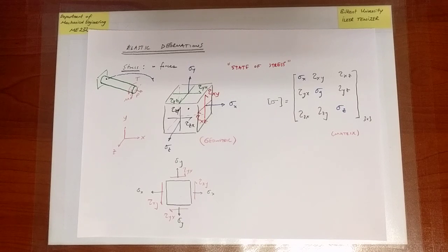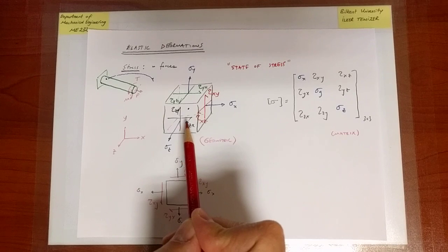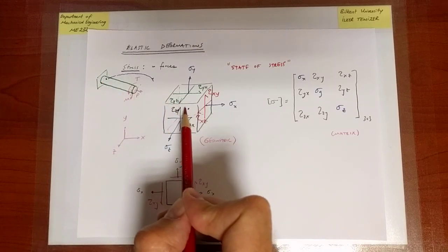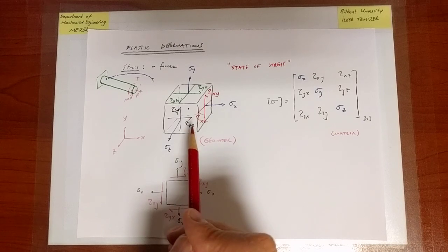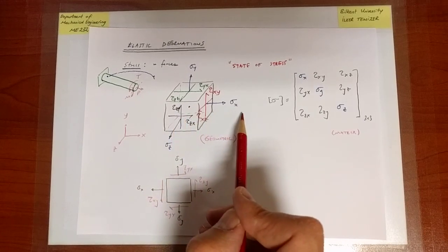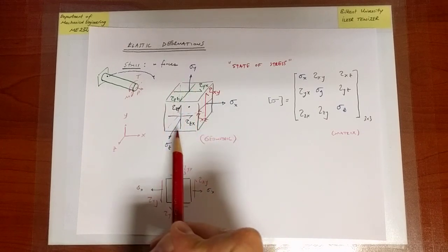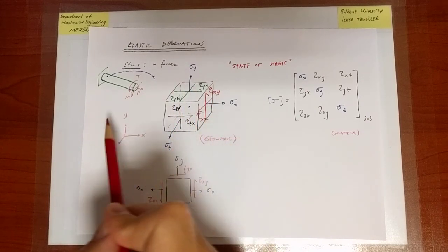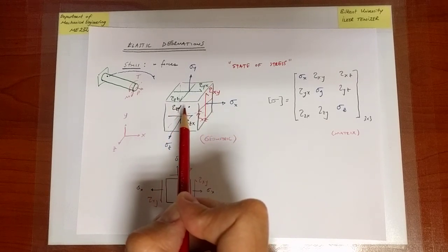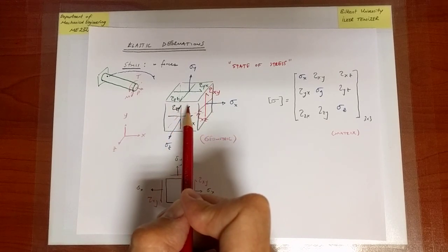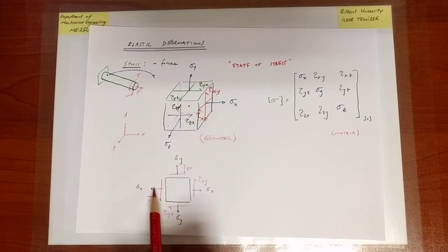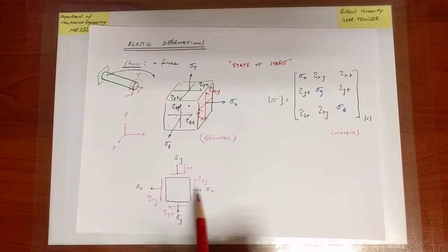Okay. So if you've thought about that question for a few seconds, then the answer is as follows. First of all, let's remember, why do we have stress components on opposing faces as well? We do because it's a small piece of the material in the vicinity of the point I'm considering, and this material needs to satisfy equilibrium with respect to forces. But remember, it also needs to satisfy equilibrium with respect to moments about any point that lies within or outside of that tiny infinitesimal cube of material. And that requires more than having equal and opposite magnitude stresses on each face.